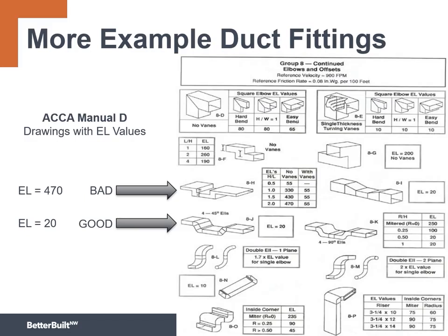Absolutely. Well, I urge everybody to become familiar with fitting types. There is sort of a shortcut. Essentially, a fitting to be considered good is if the EL of that particular fitting is below 20 feet. The medium option is basically going to be between 20 and 50 feet, and the bad is over 50 feet. And we shall see that some of these fittings are really bad all by themselves.